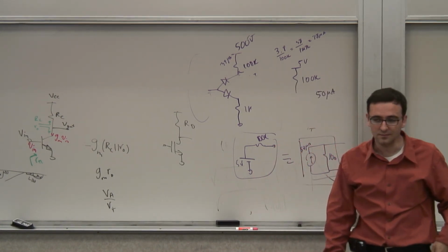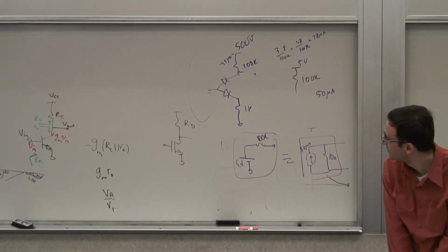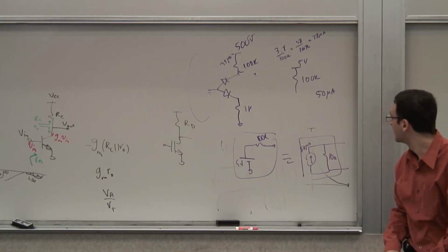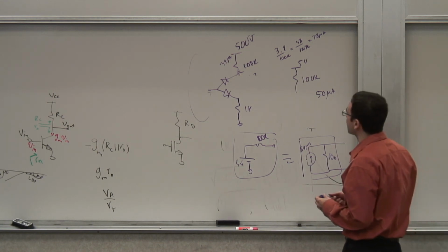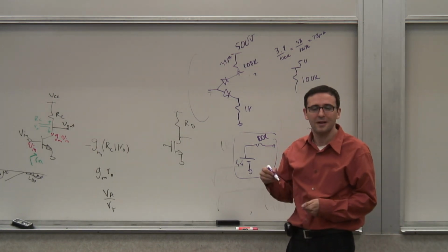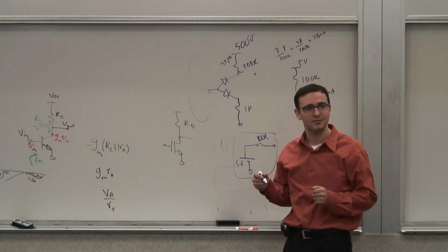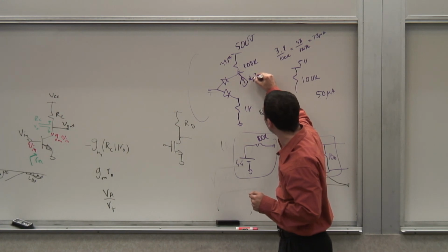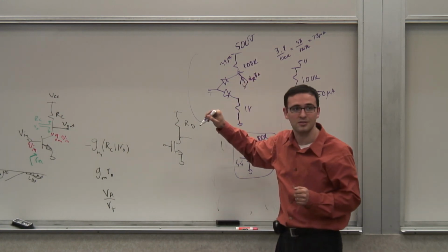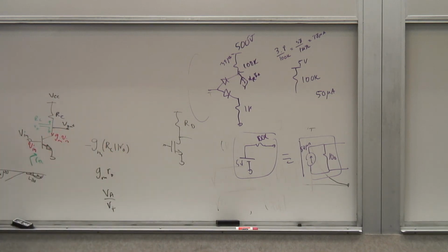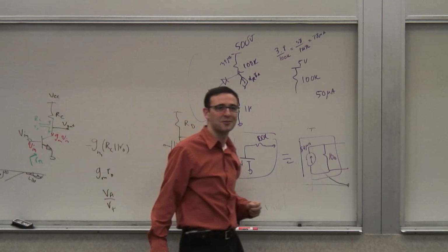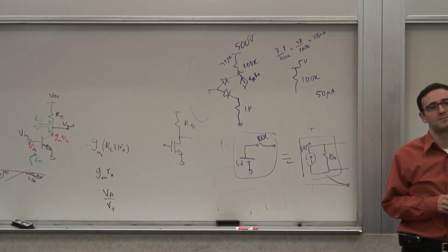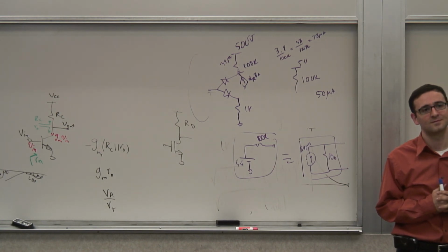Yes? In the forward active case, there are two diodes. Doesn't there need to be a DC path from the emitter to the collector also? Yeah, see, that's the thing. So actually you're right. So this is not exact. I still need that current source. See, the forward bias is provided by that alpha R current source. You're right. Even in that case, you need that. So take it back. Even in that case, my two diode equivalent, I can't even get that to work for something. You're right.